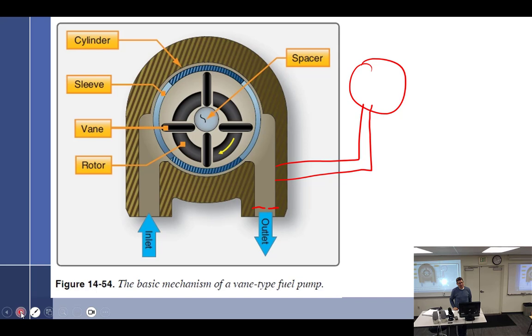Okay, a fuel injection system is very different. It's closed off from that. The Bendix system does use Venturi and air and stuff, but does Venturi work at idle? No. So we're going to see this where it doesn't really work so well in idle. You just have to have some springs, and you make it a kind of dumb thing. Because we're at idle, so here you get this much fuel. The Continental system doesn't even have a Venturi. It doesn't even measure fuel ever. So it works on a completely different principle.